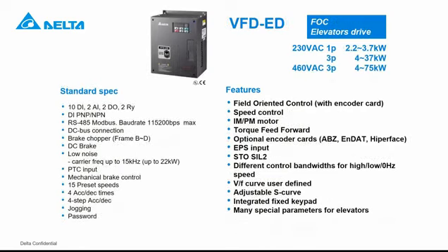And finally, the last drive that I would like to talk about is the VFD-ED. So this is a drive specifically designed for elevator applications. It supports field-oriented control with an encoder card, and it supports different types of encoders, which are popular in the elevator industry. It also comes with built-in safe torque off up to safety integrity level 2.